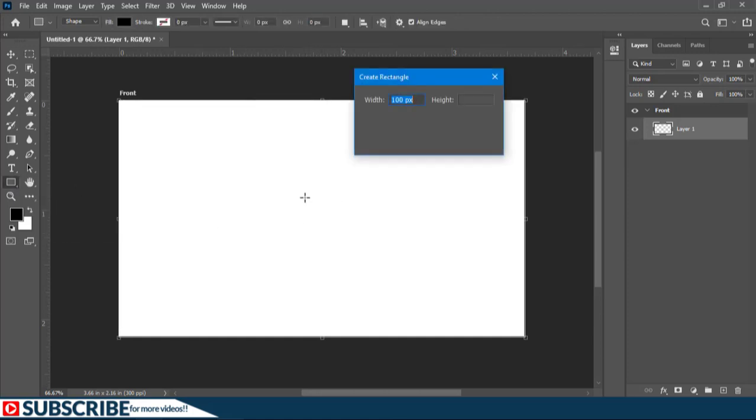and I'll select this layer, then grab my rectangle tool, just click somewhere on the canvas. Now I need to input the standard dimensions of a business card here. So for the width, 3.5 inches will be 1050 and 2 inches will be 600 pixels. Then just click on OK.